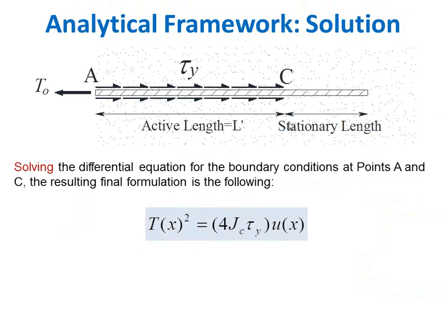If our assumptions are acceptable, then what this means is that the tension in the reinforcement squared, as a function of x, is directly proportional to the displacement at point x. And the constant of proportionality is a function, and that's why this is truly a composite behavior, because this constant of proportionality depends on the stiffness of my reinforcement and on the interface shear characteristics.